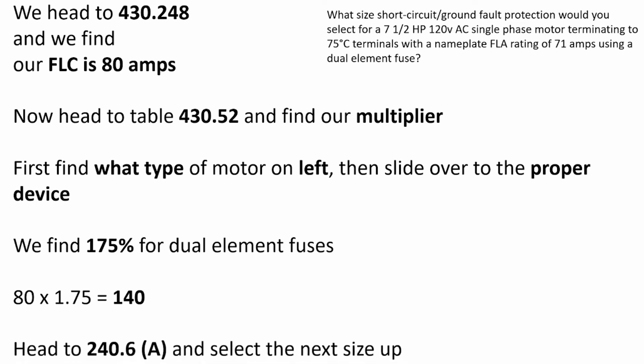Now we just head over to 240.6(A) and we select the next size up. And if we look, we're going to find 140. And which one's the next size up? Looks like it's going to be 150.